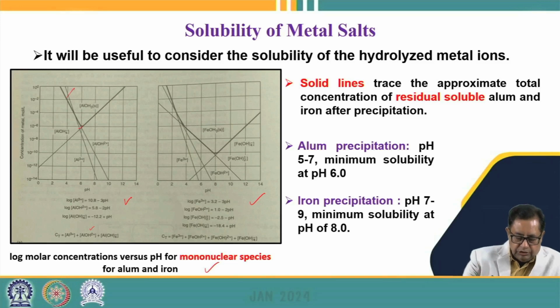So here we can see that there can be different species which are soluble in the wastewater. For example, when we talk about the alum dosing, here we have Al3+ species, AlOH2+ species, and Al(OH)4- species. These species constitute the dissolved form of the aluminum salts. Whereas Al(OH)3, which is the precipitate, may be formed, because the solubility of the aluminum decreases as the pH increases.